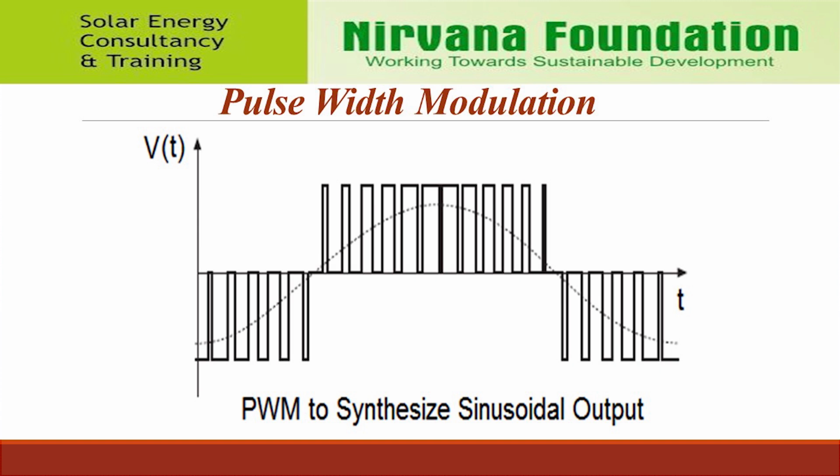Pulse width modulation, PWM, is the most effective means to achieve constant voltage battery charging by switching the solar system controller's power devices. When a battery voltage reaches the regulation set point, the PWM algorithm slowly reduces the charging current to avoid heating and gassing of the battery, yet the charging continues to return the maximum amount of energy to the battery in the shortest time. The result is a higher charging efficiency, rapid recharging, and a healthy battery at full capacity. PWM ensures longer battery life, more battery reserve capacity, and greater use of the solar array energy.